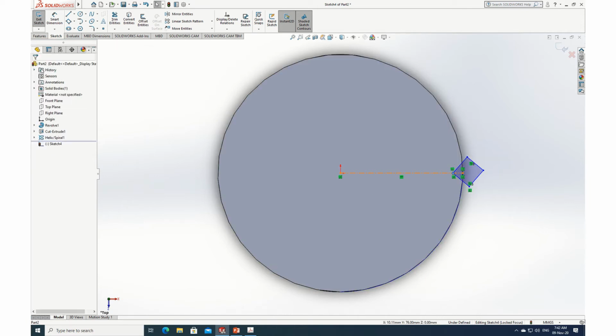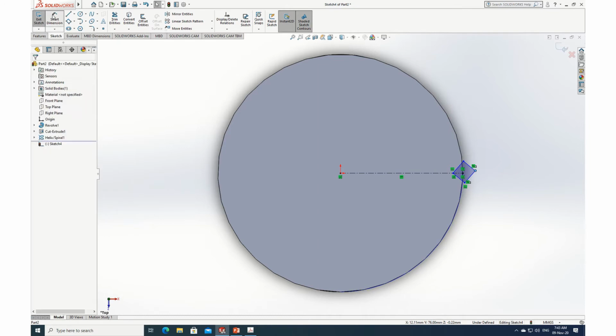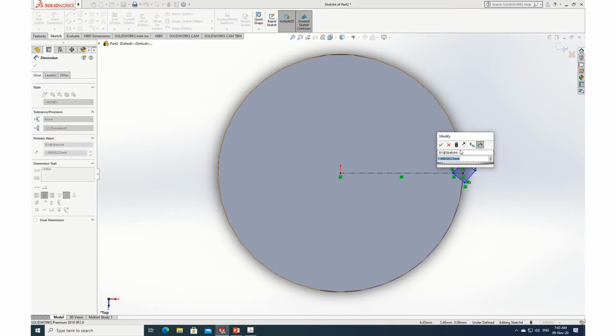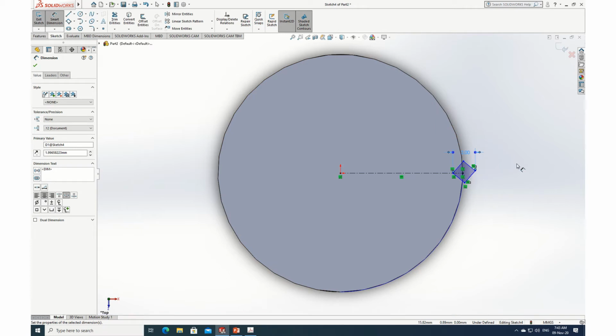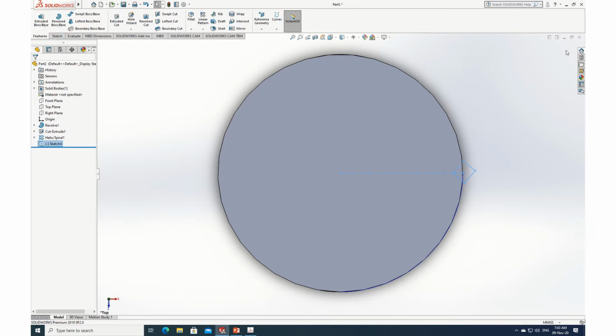Okay, now what else is there? I can just push it little bit inside. I have it here. Let me select the dimension. I am only showing you typical. So 1 mm it will cut inside almost. This portion will not cut, it will be outside. Only this portion will be cut in the material. Right. So now I have finished it. I will exit out of this sketch now. See here on the right side, I exited, it became blue color.